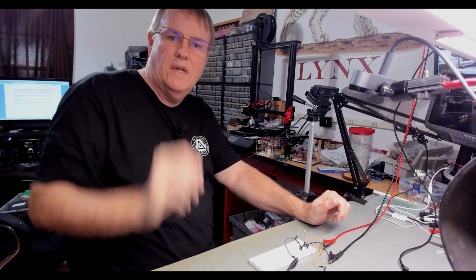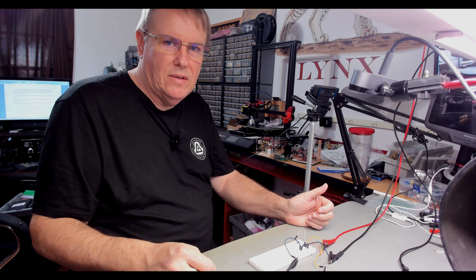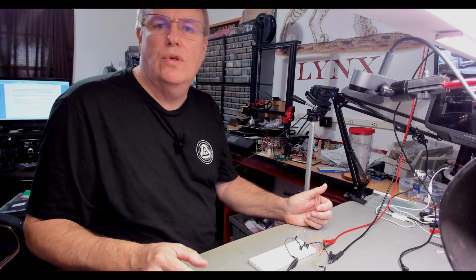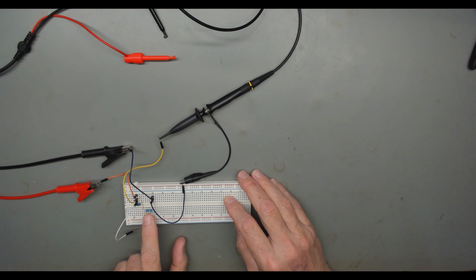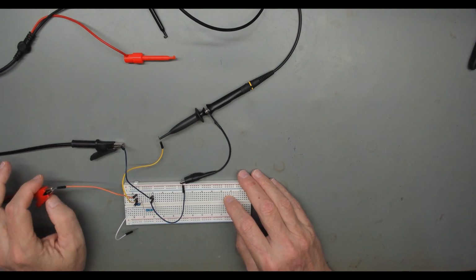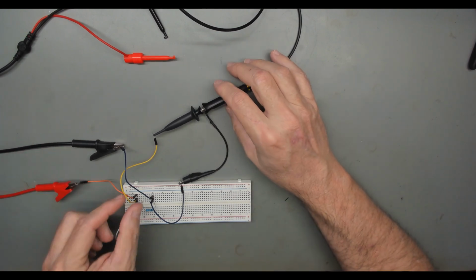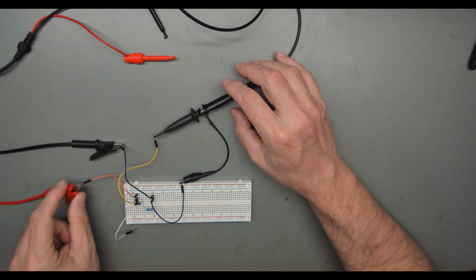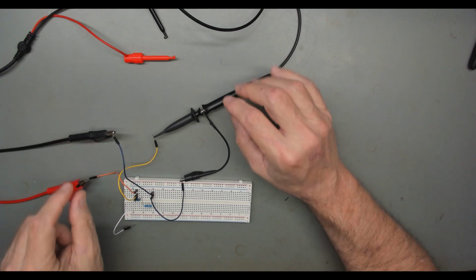Okay, I've got set up a little test rig here. I think the first important thing to do is, before I try to explain to you why a capacitor blocks DC and allows AC through, it's very important that we prove that's true to you. I've set up a little jig here. It's very simple. I've got a 10 microfarad capacitor in series with a 10 kilo ohm resistor. And I've got my DC power supply set up here, and I've got my oscilloscope set up on channel 1. And I'm currently looking at the input to the capacitor. So you have the input of the capacitor, runs through the capacitor, through the resistor to ground, back to your ground, and I've got my oscilloscope across ground and the input.